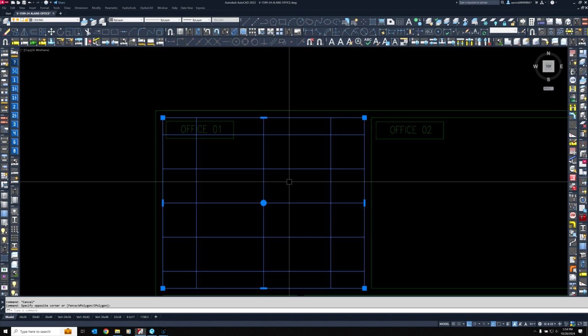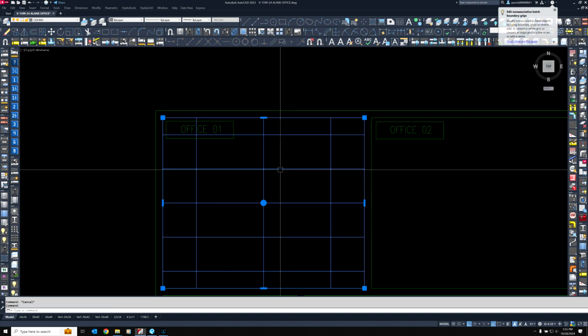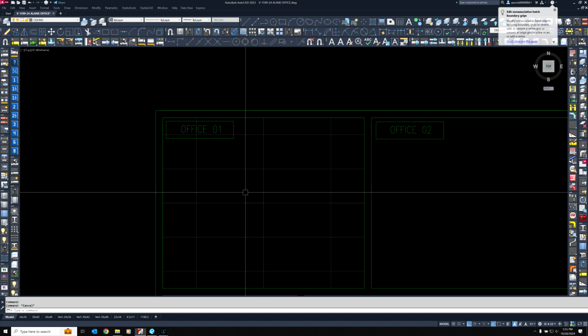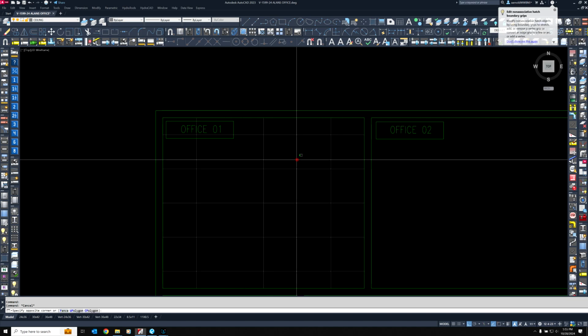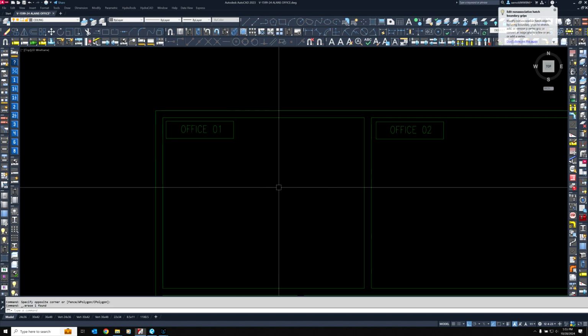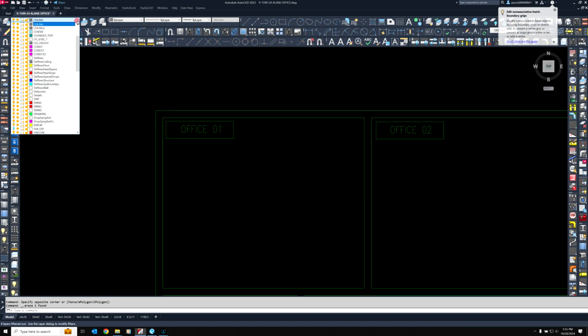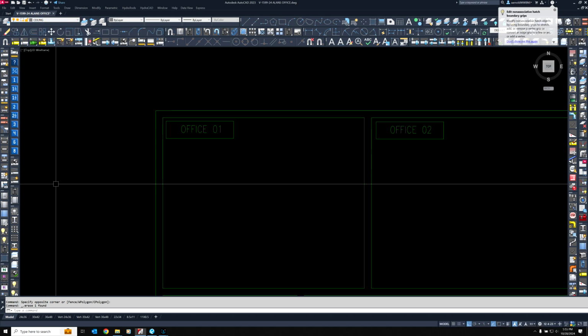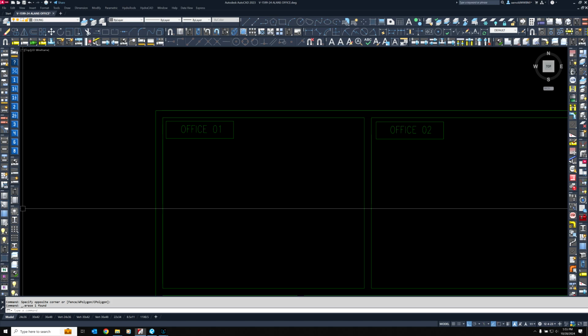If you need, which really you end up needing, typically we have to explode this so that we can insert the lights and the diffusers. So let's just do this all at once. I'm going to delete that. Remember, we come up here to layers, select ceiling.